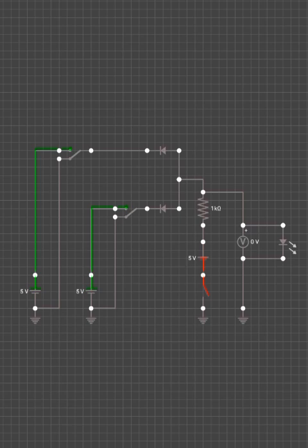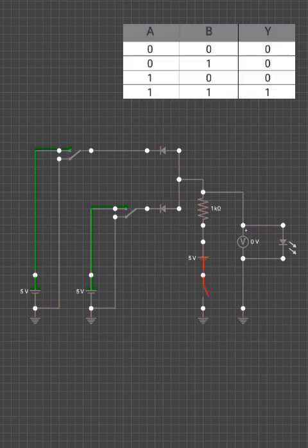The output of the AND gate is high, or 1, only when all its inputs are high. Saying this in truth table form, the output Y of an AND gate will only be 1 when the inputs A and B, C and D, depending on how many inputs, are all ones. And this is the reason it is called an all or nothing gate. That's the other name. So let's dive in.